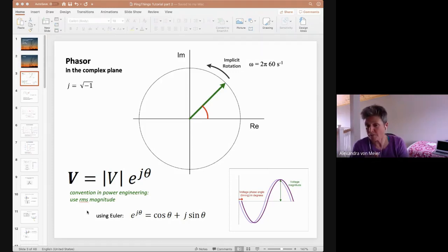That is not obvious, but it's the thing that synchrophasors or PMUs are measuring. And you have to have a common time signal from GPS or other shared high accuracy clock in order to accomplish that, because the difference in timing we're talking about is very tiny fractions of a second.